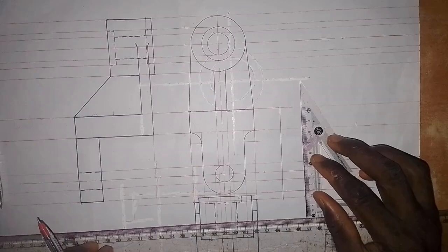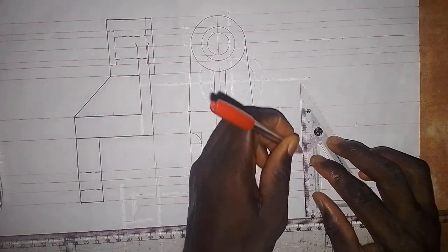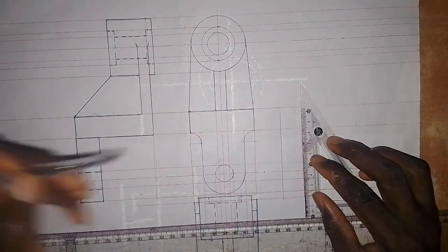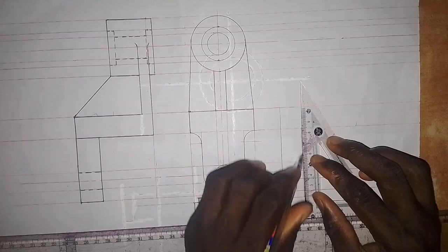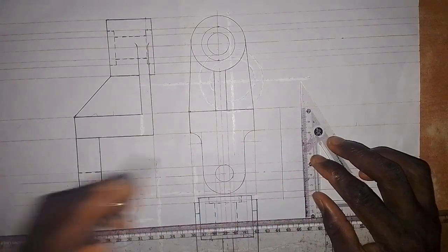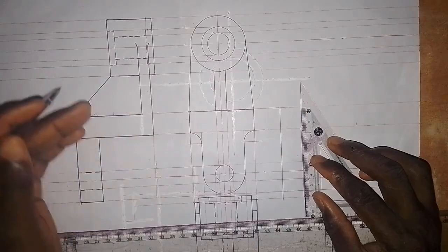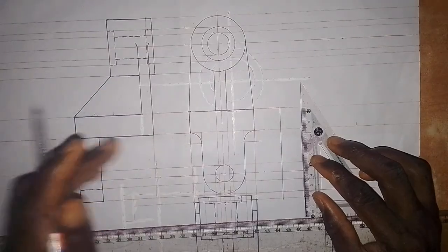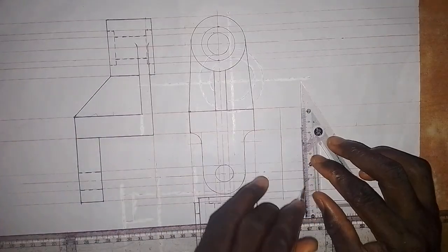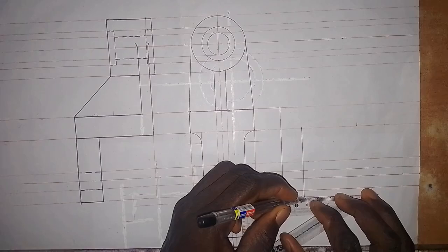So I'm going to draw this line from here. I will draw it up to this level. In this case, it will not be a thick line all to this end. This line here, we are not going to make it a thick line, so we leave it just like this, because that part is cut off, so this line will not be a thick line again. We just leave it like this in the end elevation, and this line will become a thick line.